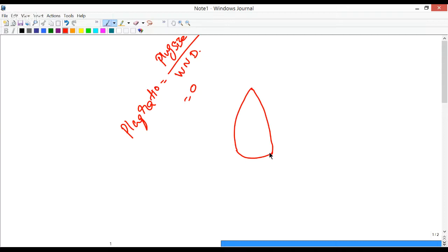Assignment 3, question 4. Which one of the following controls the stability of the keyhole during laser welding of galvanized steel in overlap configuration? So this question is related to the videos I showed you when we were doing galvanized steel welding in overlap configuration. The zinc vapor determines the keyhole stability. So the vapor pressure determines the keyhole stability when you are welding galvanized steel.